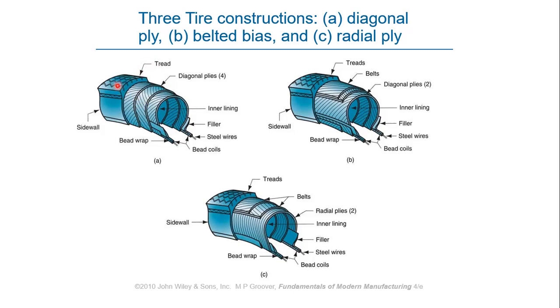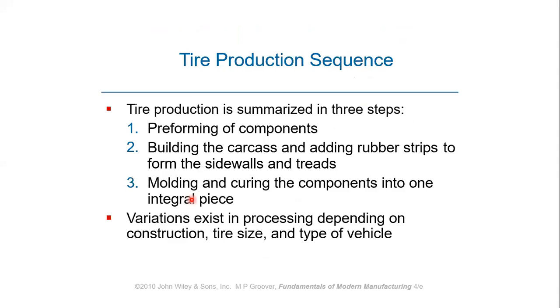Finally there is the tire tread, along with the sidewall. Sometimes the treads are provided in the die where you manufacture the tire, and sometimes they are cut separately, after manufacturing the complete tire. The ply orientation can be different, like this one has one ply orientation and this one has another. That means the fiber orientation in the rubber sheets. The sheets are produced separately, and then they are stacked one after another, and then the curing occurs.